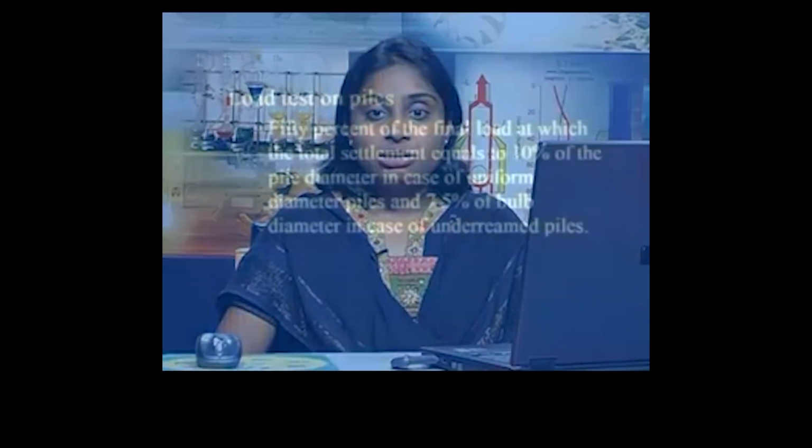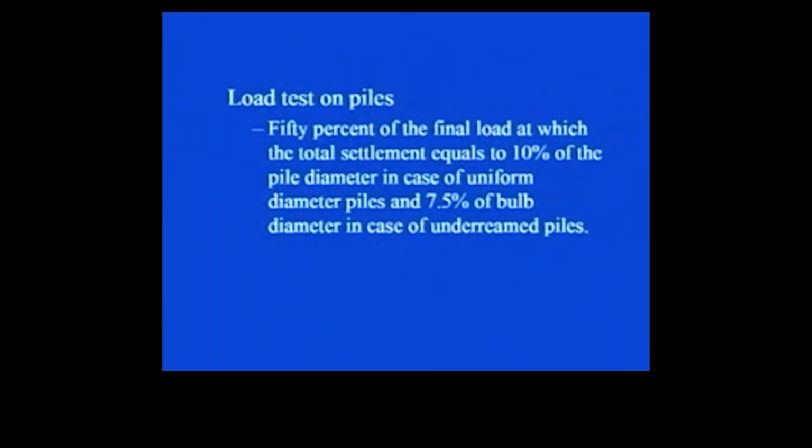So, whatever is mentioned, you have to take the load corresponding to that. If nothing is mentioned, you take the load corresponding to the 12 mm settlement, and if some settlement value has been mentioned, depending on the type of soil and the structure, you have to take the allowable load corresponding to that much settlement. Then 50% of the final load at which the total settlement equals 10% of the pile diameter in case of uniform diameter piles, and 7.5% of bulb diameter in case of underream pile.